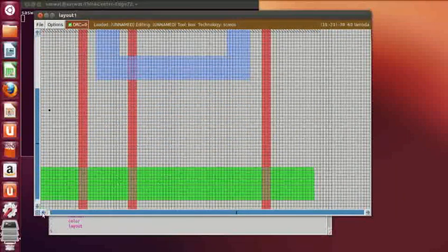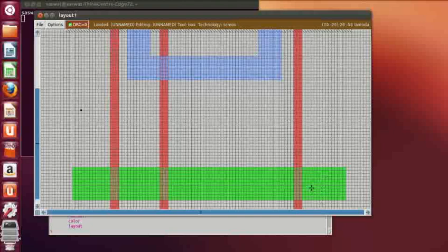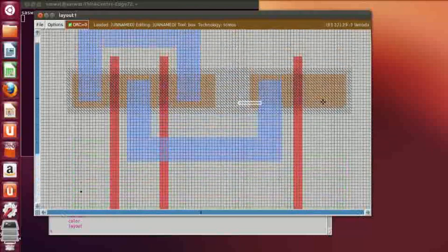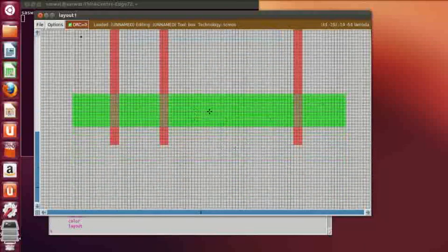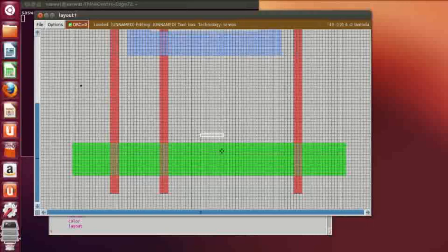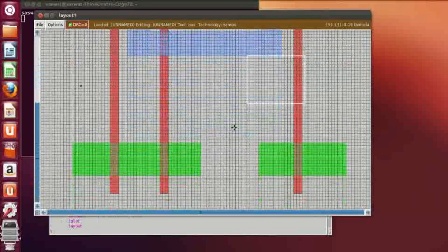This is the NMOS part. In the NMOS part, the drain of the first NMOS and the drain of the last NMOS, that is the third NMOS, are not connected. The source and drain are shorted, and this drain is connected to the drain of this PMOS. So before going for that, this is the source of these two. You can do one thing just for a good alignment. We'll short these two, S2. So I'll erase this part, so that this looks a bit aligned and proper.